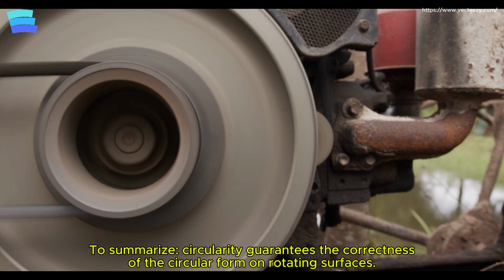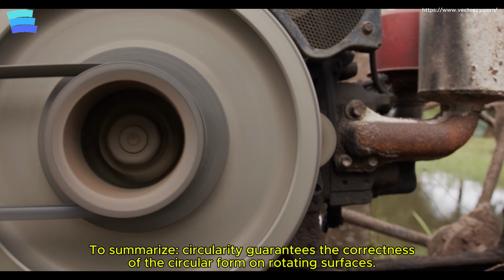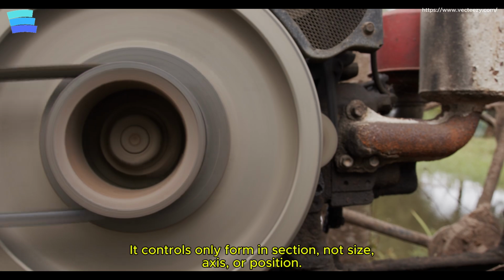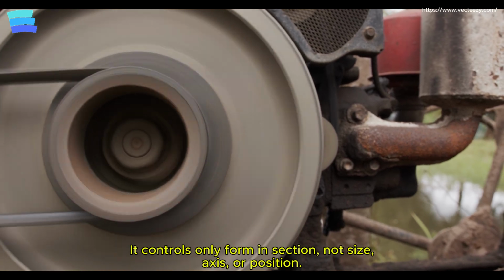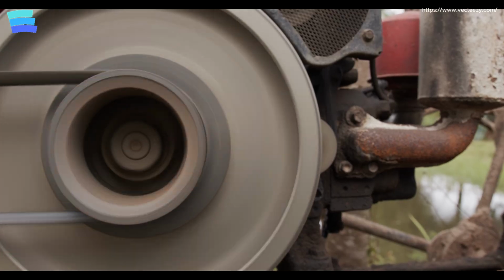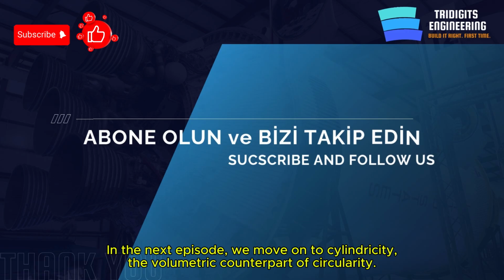To summarize, circularity guarantees the correctness of the circular form on rotating surfaces. It is not a control of size, axis, or position, it controls only the form and section. In the next episode, we will move on to cylindricity, the volumetric counterpart of circularity.